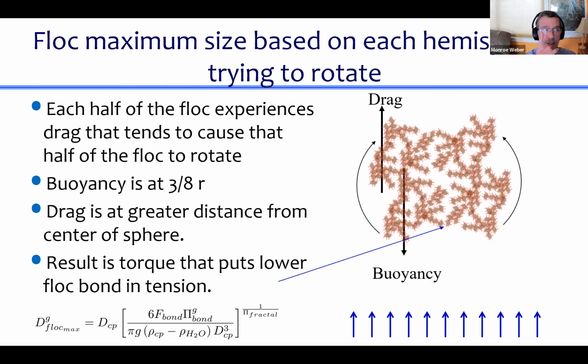And remember, this is another key idea. We have the idea that these flocks form by rolling together. I just realized that I made an assumption there that wasn't necessarily accurate. Okay, so let me step back. In the flocculator, we've learned that only similar sized particles can collide because of their boundary layers.